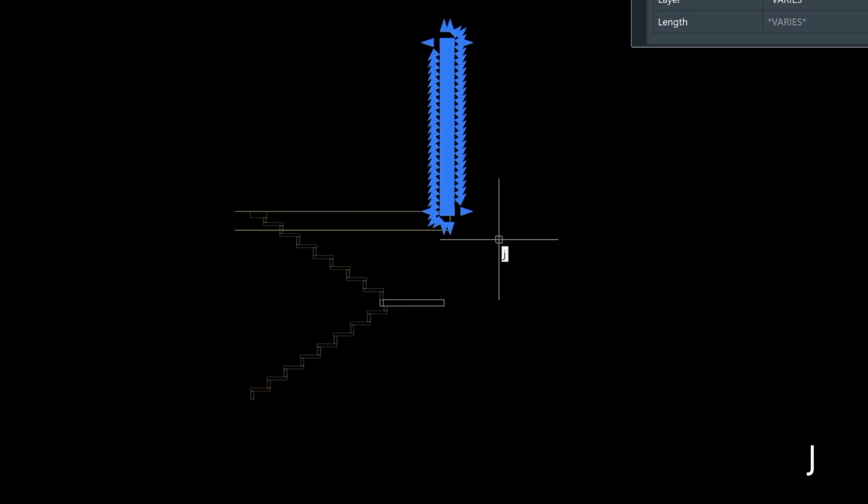So you can see what I've got is my wall, my floor, really a section of what's going on in the stairs. So from this elevation, I'm going to build my 3D walls using the Extrude tool. First, I'm going to go ahead and explode this, explode it twice here. And then I'm going to take this wall here, and I'm going to type J for join, and that's going to join everything together so I can manipulate this a bit better.